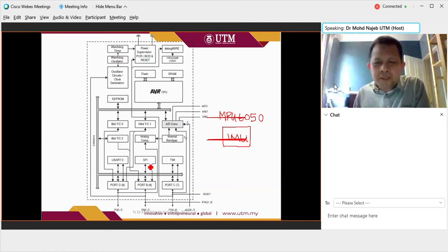Remember, onboard connection. You have some other ICs together with your ATmega328, and then you can write to this IC serially, send digital configurations, and then you can read back digital data reflecting the motions inside the IMU. And then we have the TWI, or we call it two-wire interface. Two-wire interface.